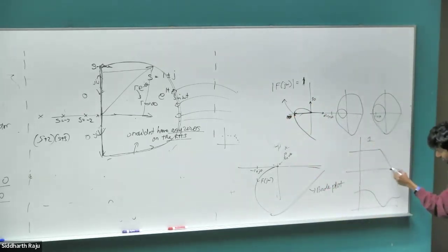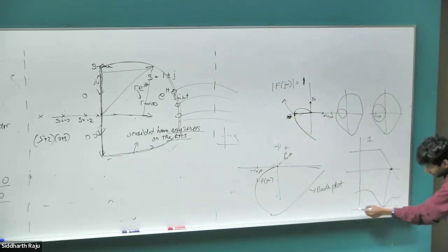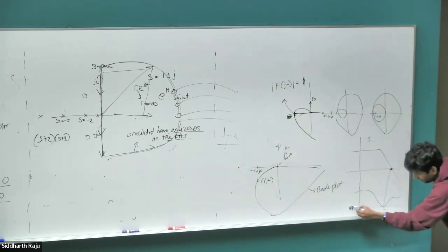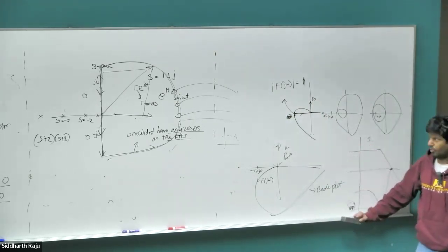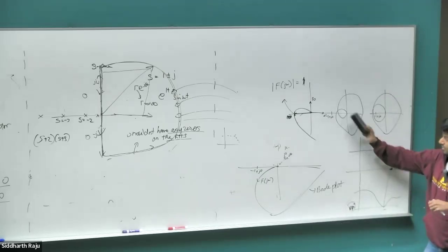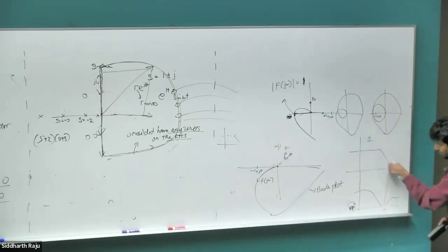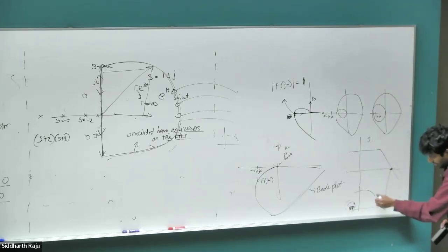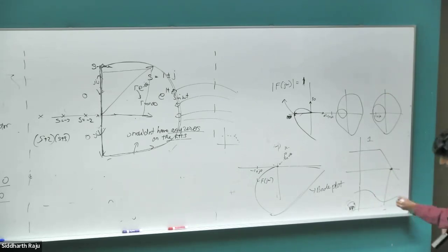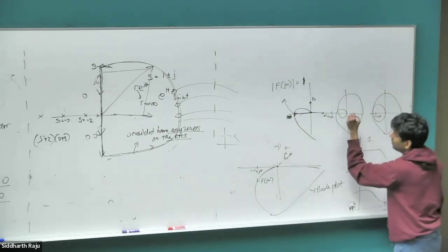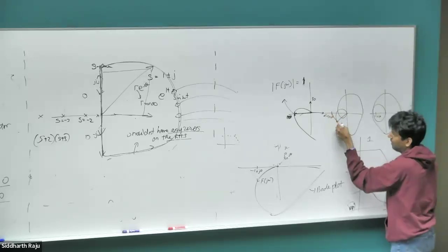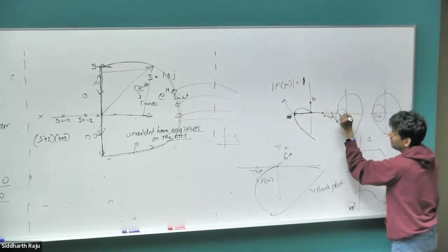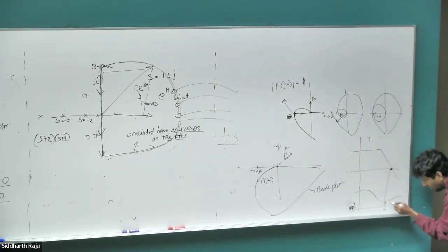So if I look at the plot where that crosses over, and if this is 180 degree or negative 180, both same, then that would be the condition between stability and instability, which we would qualify as unstable. For this case, where the magnitude of the log plot is 0, our phase plot would be far away from 180 degree, right? There's going to be some kind of margin. So if you look at this, where the magnitude of this vector is equal to 1, if there was enough delay in the system that it gets rotated a little bit leftwards, then it will become unstable. This difference is called the phase margin, how far away it is from becoming unstable.